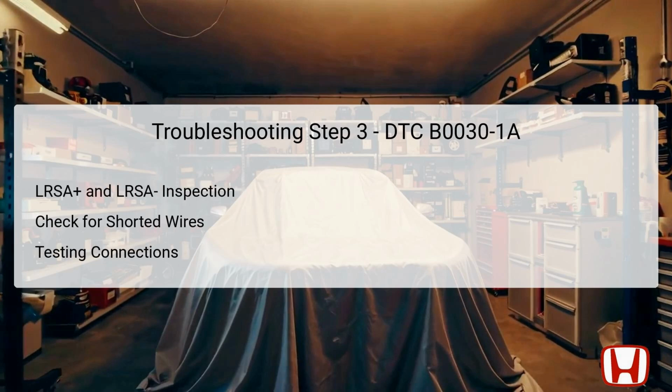The third step focuses on inspecting the LRSA Plus and LRSA Minus circuits for possible shorted wires. Begin the process by disconnecting the SRS unit connector B and the left rear side airbag inflator connector. After ensuring that both connectors are detached, connect the appropriate terminals from the SRS unit connector B to the SRS short canceller. With the vehicle in IG mode, conduct a wire inspection to determine if there are any shorts within the LRSA Plus and LRSA Minus lines.